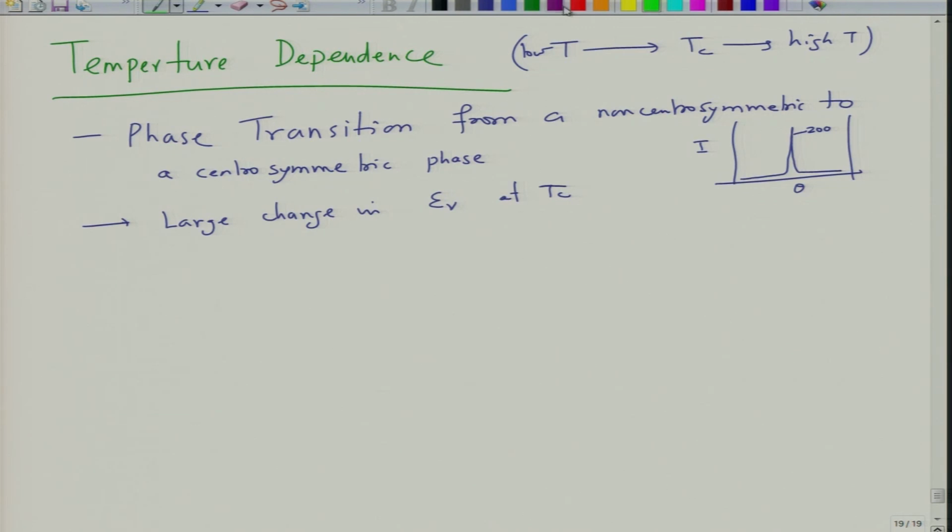When you take a temperature dependent XRD, this will show a splitting. So, you will have a 020 and then you will have a 200. So, this is cubic and this is tetragonal. This is how you study the phase transition. So, this will be 200/020 and this will be 002. So, you will see a clear peak splitting. You will have a change in the XRD peak profile because of phase transition, and this phase transition is because of subtle change in the crystal structure which goes from non-centrosymmetric to centrosymmetric, that is from tetragonal to cubic.